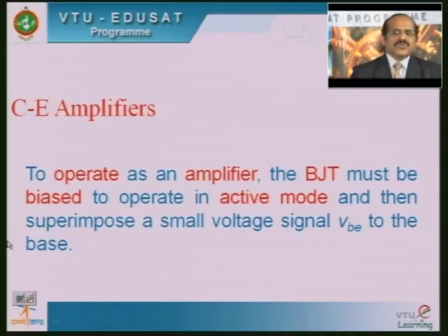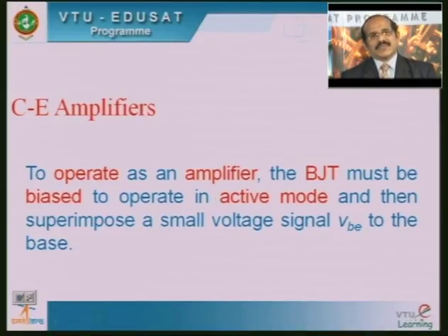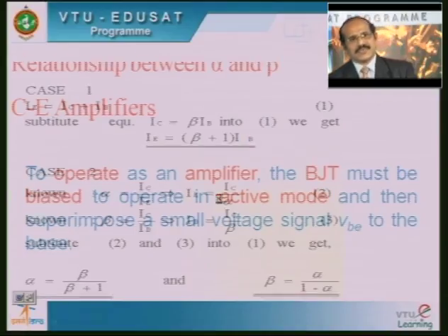And you know that usually to operate a BJT as an amplifier, we prefer the common emitter configuration. It is only because this will provide more current gain as well as more voltage gain. And also it should be noted that to operate the BJT as an amplifier, we make use of the active region, where the output characteristics are linear and there is an equal distance between the neighboring curves here. Which is very important as far as faithful amplification is concerned here.